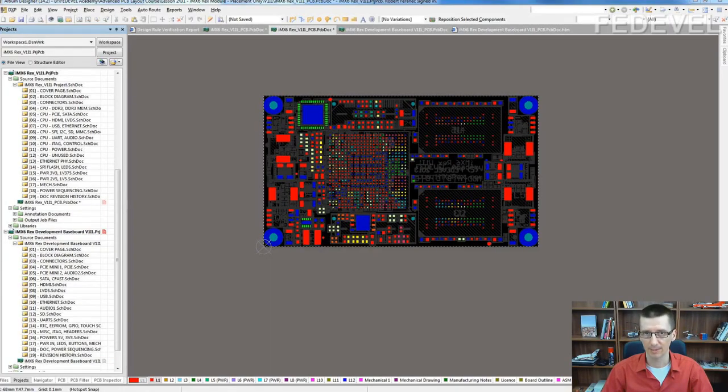The module PCB, that's something completely different. This PCB will be manufactured by a company which has advanced PCB manufacturing technology, and they usually can go as low as 75 micrometers for the minimum track and minimum clearance. That's 3 mils. But I always start routing this kind of design with minimum values such as 0.1 millimeter minimum track and 0.1 millimeter minimum clearance.